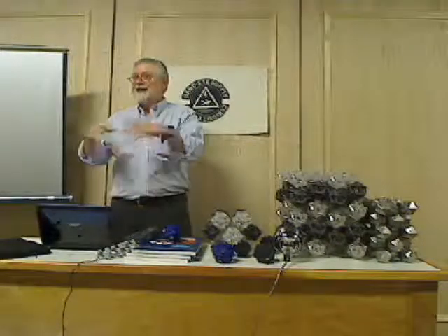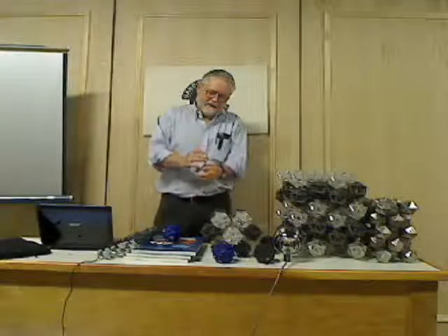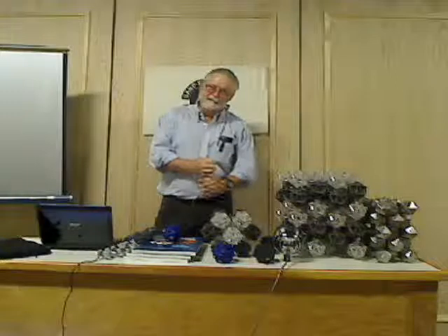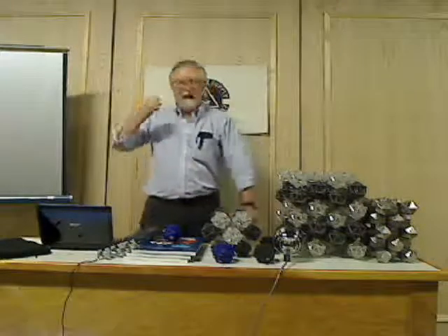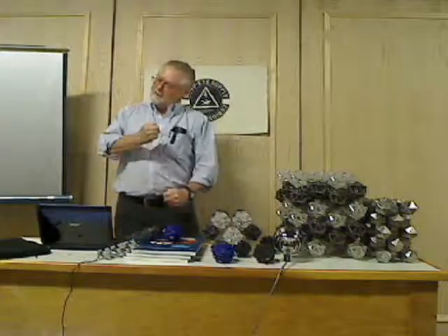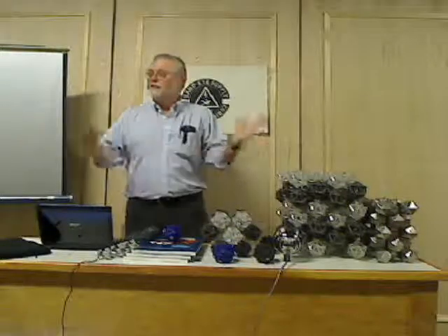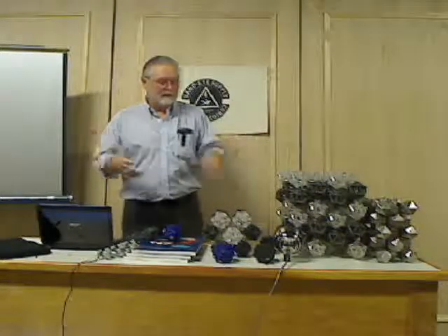So with steels, and this is what they do to determine elasticities, they take common steels, so maybe you added nickel to it, maybe you got a stainless steel now, and they give it a common form factor, and they literally have presses that just pull it apart. How much that stretches gives you the modulus of elasticity. That's stress over strain. It's a very important number to know. The other important number to know is when does it break? Not just how much is it going to stretch, but when does it break?